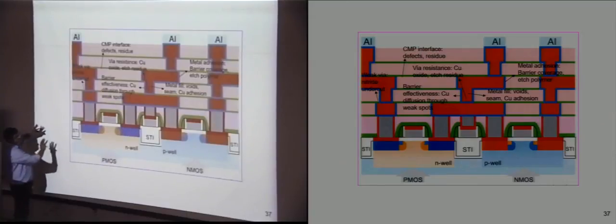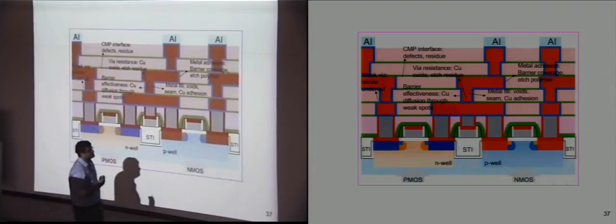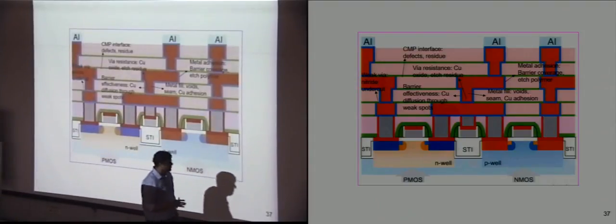So let's say just like you have these patterns over here, you may have a rectangle or a triangle, a test structure made of the copper grown over here or grown over here, and during the inline inspection you would check the quality of the copper. Okay, so in that way you can try and make sure that your devices are functioning and the layers you have deposited are accurate.